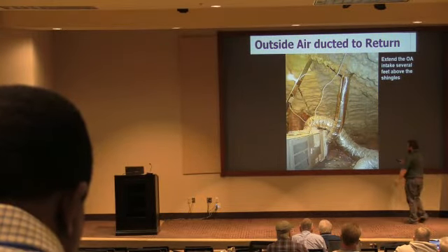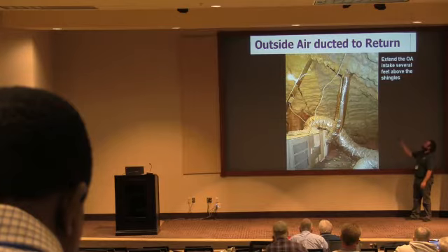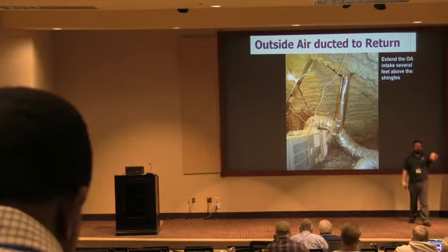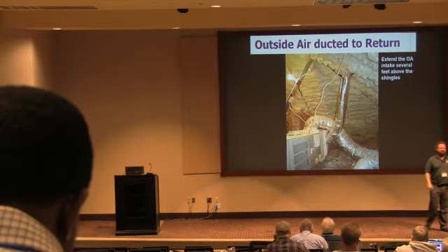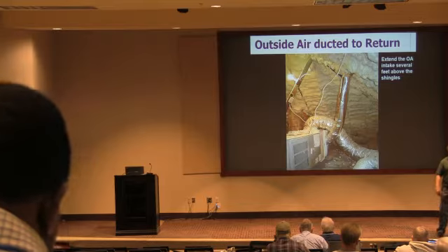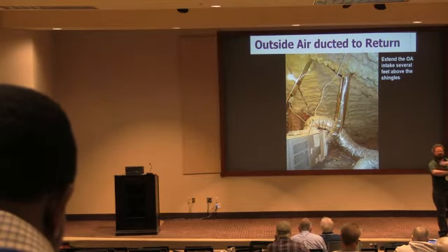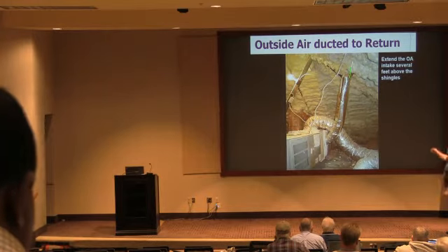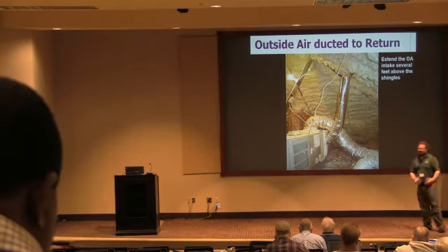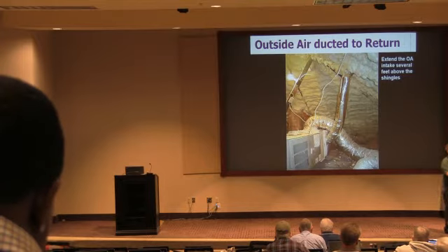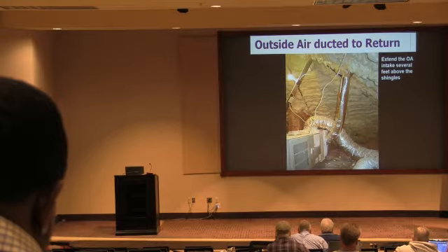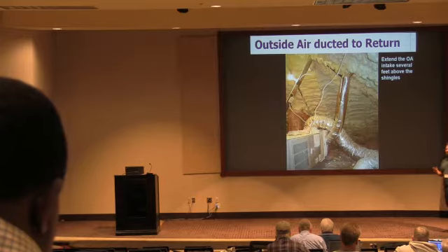This is the same type of system, but instead of coming off of the sidewall, they're just coming in off the roof. The big thing about this is this should not be drawing air 4 inches off the shingle. If I'm going to bring outside air into my house, do you think I want to breathe what's coming off of a baking shingle in the summer? Probably not. So this needs to extend several feet up above the roof deck so that we've got a mix of air coming into it. But we see them all the time drawing air 4 inches off of that baking roof shingle, and that is bad.